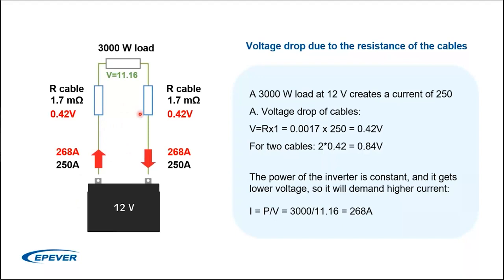And one of them could be the voltage ripples, the DC ripples in your system, because this will happen frequently, and the battery will try to compensate for the amount of the current that is needed. Then you will have a ripple, and this ripple will shorten the lifespan of all the components in your off-grid system.